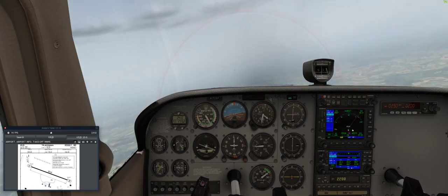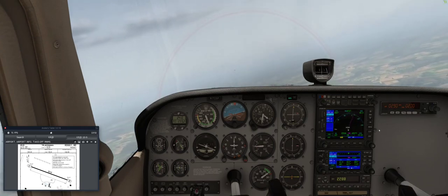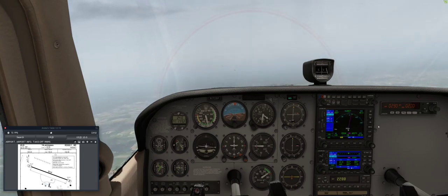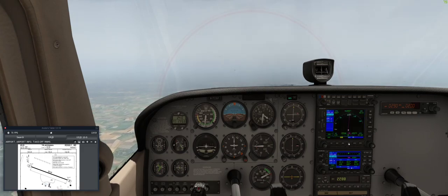And you see it just automatically activated the next leg because we're close enough to that waypoint that the GPS system considers us there, and now it activates the next leg. And you can see that if you bring up your flight plan to view it, as you reach each point, it rolls off the flight plan and the next one gets the magenta arrow, becomes the active leg. That all happens automatically.